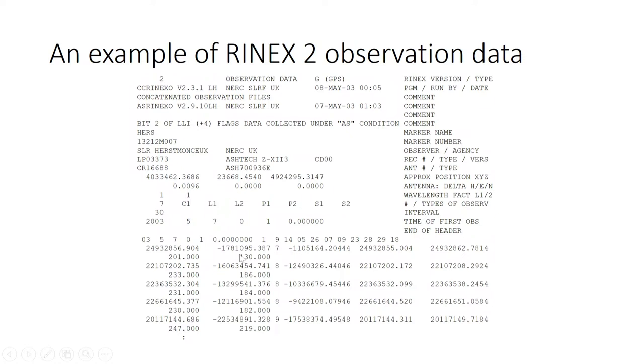Depending on your requirement, you can acquire every second, a 15-second sampling interval, 30 second, 60 second, depending on your objective. If you are looking for a very slow continuous movement that you want to monitor, you have to do the kinematic measurement, which can be done at 1 hertz sampling interval. If you are doing tectonic study, you can collect at 15 second or 30 second. These two are preferable for tectonic measurement.